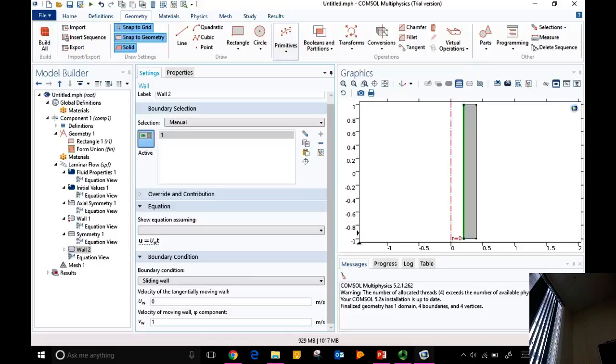So this is the central part, right? And you're pulling it, but you're immersing it in a polymer. You want to coat that. So as you're pulling it, this has a velocity like this. And then what would the velocity profile look like? This is why I said on any surface, there is one normal, but there are two tangents. In this case, one tangent is in the z direction, the other tangent is in the phi direction. So you need to identify what the two components are there.